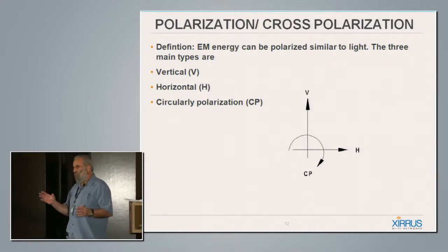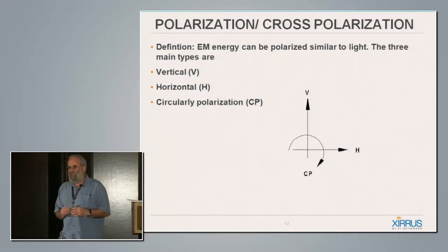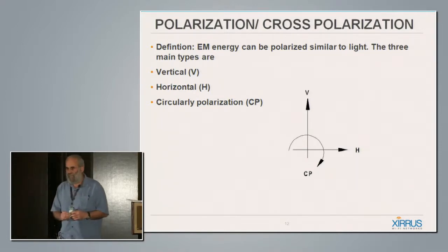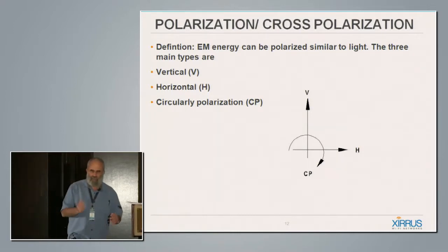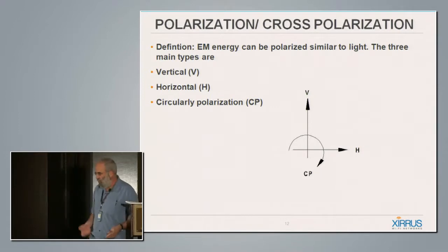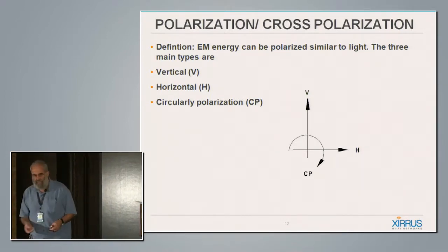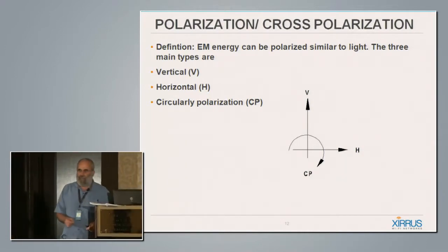It's important, especially with directional antennas, that you co-polarize with your receiving end, even though the receiving end could be many users. If they are especially mobile units, the orientation of the mobile unit can be anything, and you cannot cover all of them.